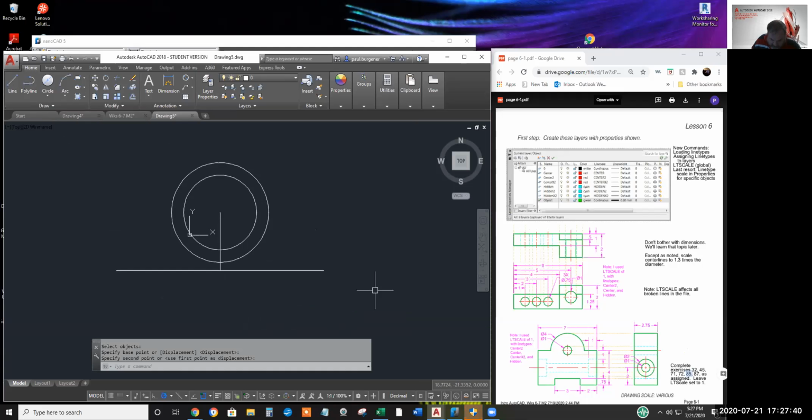And we can offset this guy 10 and 13 upward. Offset, space 10. Enter to finish, enter to invoke the last use command, change the setting to 13, enter, pick the same line there. And we'll put lines at the ends, enter, enter.